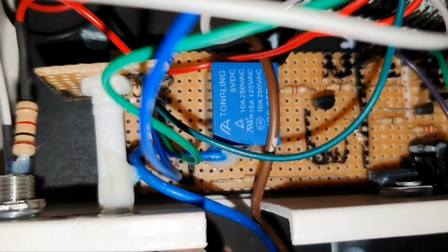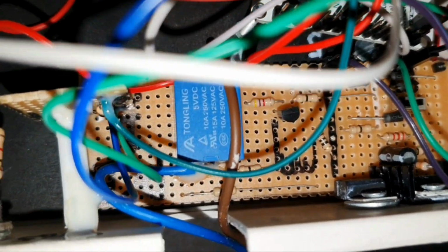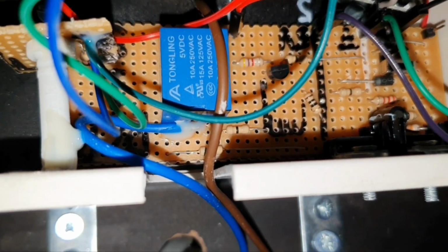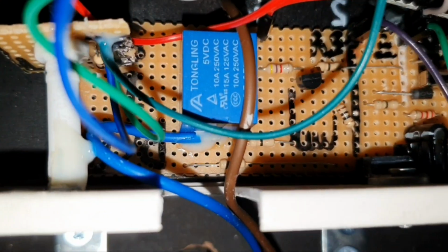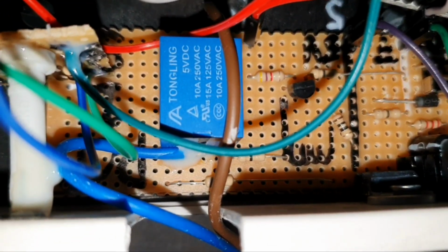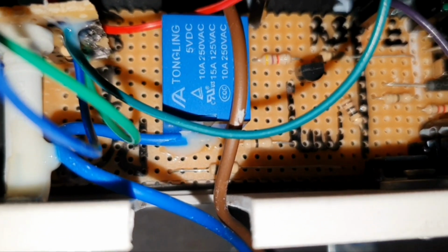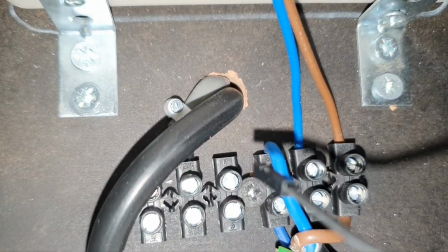This over here is the relay that switches the street lights on and off. I'm not going to touch it. I have isolated the live electricity coming into the relay. We can see the neutral at the moment and the live. Well, both of these are actually live connections because the live is just simply interrupted. So both these wires, blue and red, are actually the live wire just being interrupted by the relay.